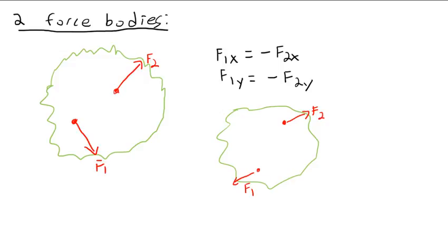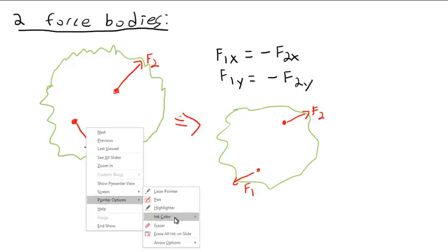So what's the only way you can prevent this from rotating? Collinear. Same line of action. We could reverse the direction on this one, then it would no longer rotate, but now it would translate. So instead we need to make them collinear. So basically we start with this generic case, then this causes us to narrow to this one, and then we say, oh, wait a minute.